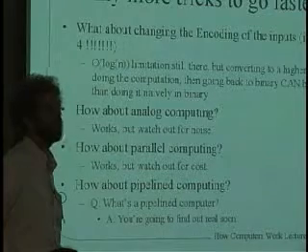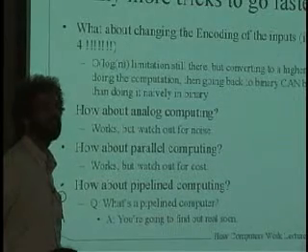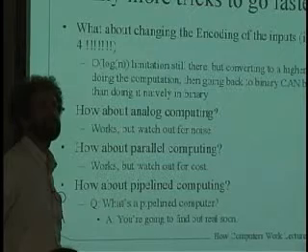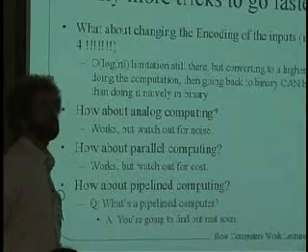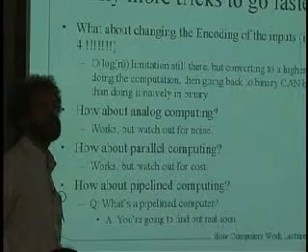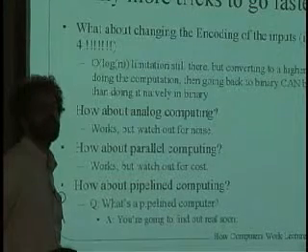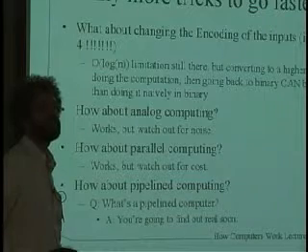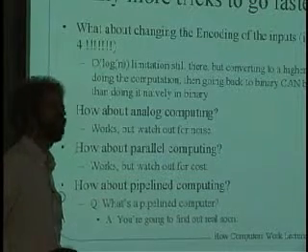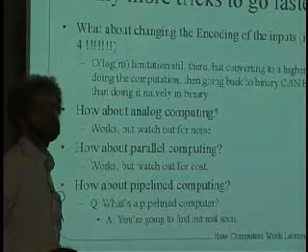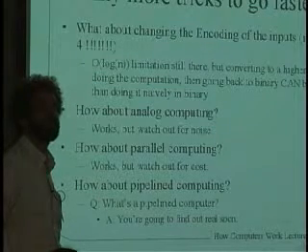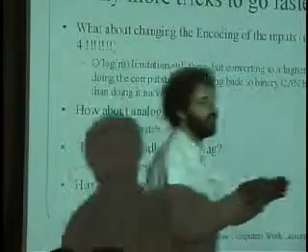And just to give you a hint as to what that is, who said that we had to do all the bits at the same time? In other words, if we thought of the 32 bits of an add as 32 steps in the assembly line of building a car, who says that one guy has to build a whole car, and then when he's done, he has to go back and build the next car? Why can't we have 32 guys, each one engaged in building a particular part of the car, and any given car is spread over the line, so that while it takes one car 32 steps to make it through, the rate at which the cars are produced is 1 every cycle, okay?